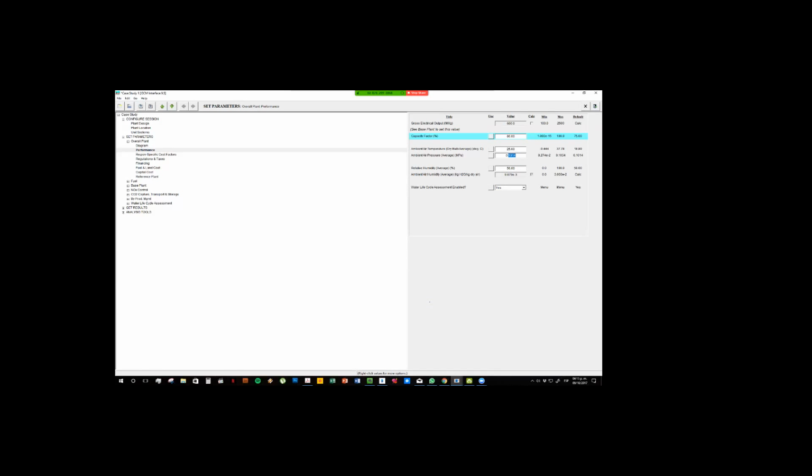So we can change it a little bit, but not as high as Mexico City. If you see here in the columns, in the left pane, we have a minimum value, a maximum value, and the default value, right? So the minimum value is 0.082 megapascals, right? In Mexico City, it's a little bit lower than that one, but we can choose that one instead, right? So I'm going to write down those values.